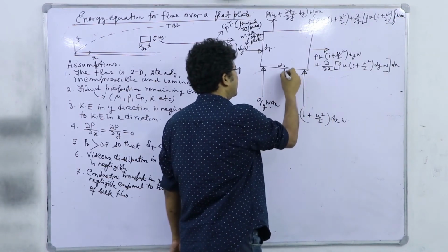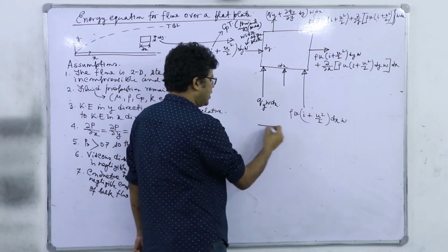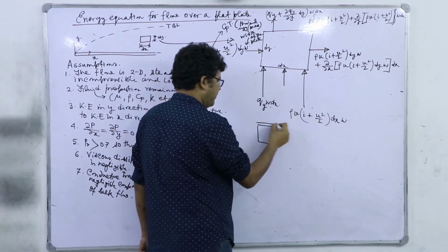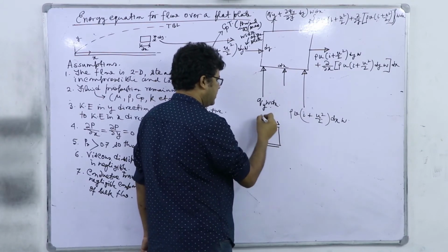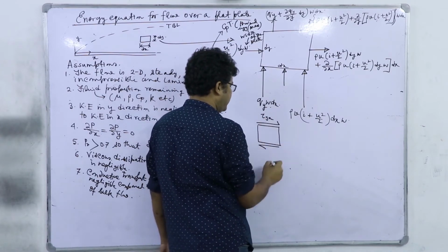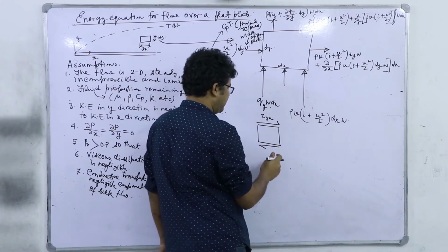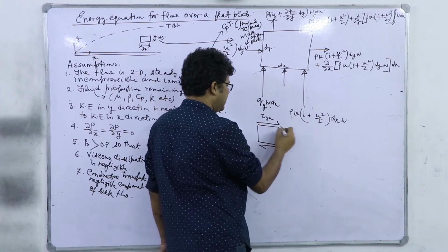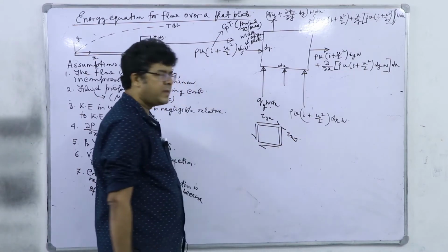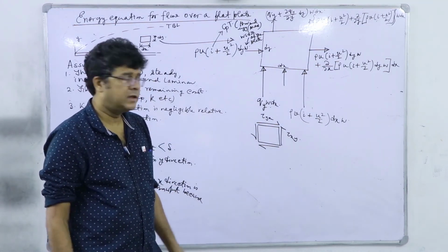Next, here comes the viscous dissipation term. Now you see, in order to explain it, on this shell I have two shear stresses. Here these are all tau yx type, the value may change. This is tau yx type, and here this is tau xy type. And we know that tau yx and tau xy are the same.